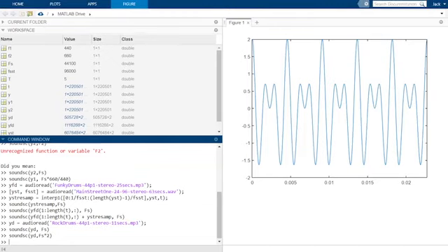Now that we know how to combine sounds using addition, we can investigate effects of additive noise. That is, noise that is added to the signal. The most common noise distribution is called white noise. This is additive, normally distributed, random noise with zero mean and finite standard deviation.